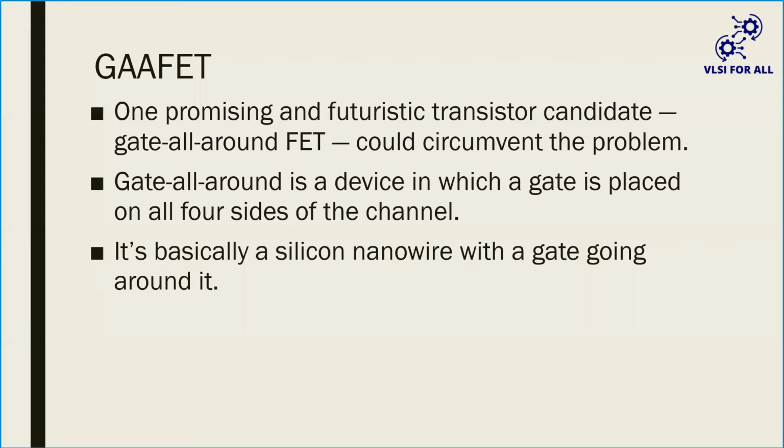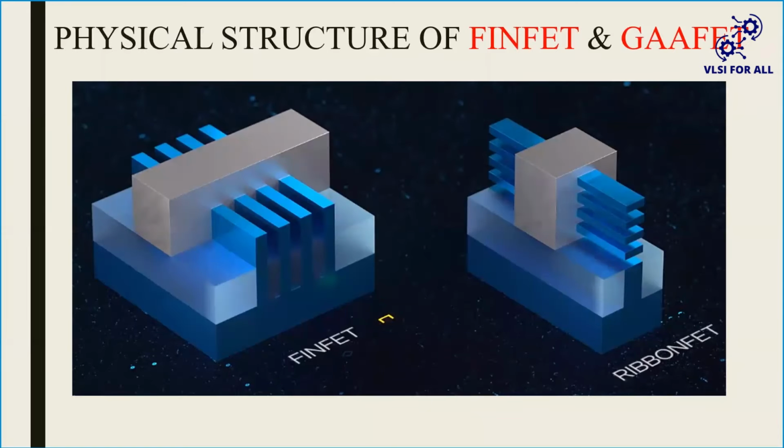Next slide. Yeah, you can see here now. The blue color ones are source and drain. There you can see the gate from top, left and right, not bottom. But in the ribbon FET, which is a GAAFET, even from the bottom side the gate layer is covering. Hence, team, in GAAFET it is happening in all 4 directions, so you can efficiently form the channel.